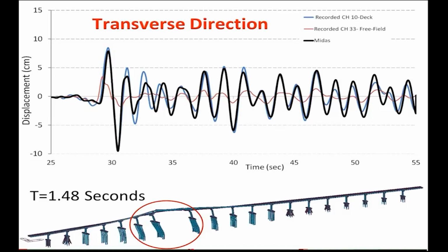Of course, this is a very complicated model. You don't expect the whole structure to move in phase in the transverse or the longitudinal direction, but in the longitudinal direction the predominant period is close to a second, and I was also able to match the longitudinal period of the model versus the recorded motion.